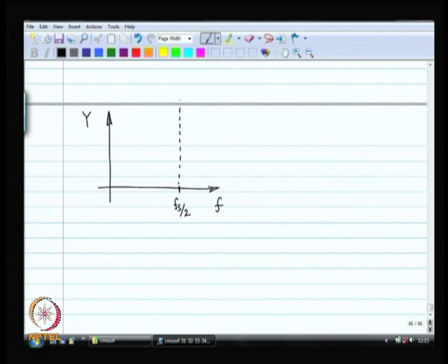In our case, we have a discrete time system, right. So, the restriction for the sigma delta or delta sigma converter is that the input is a low frequency signal. It is not changing as fast as the sampling rate. That is the basic restriction. In fact, it is changing much slower than the sampling rate.